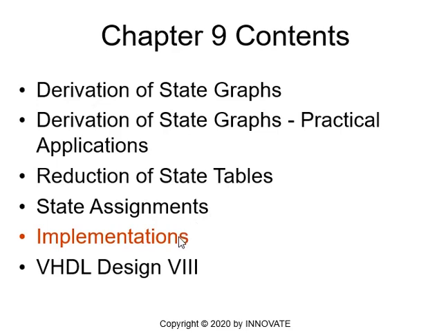Then we do implementations. Once we have the state assignments, we do implementations. And if we like to implement with programmable logic devices, we will use VHDL language. VHDL allows me to design the code necessary to implement the network. Then we can generate the netlist file and we download it to any PLD or FPGA.